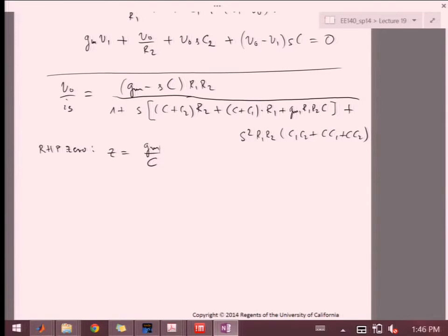And that will actually be very bad for us, as we'll see later in CMOS op-amp, because that's exactly the behavior you don't want to have. You want your gain to be lowered and your phase to be maintained, right? Because we want to decrease the gain below 1 over f in order to have gain margin. But what this does is keep your gain kind of flat instead of breaking it, while it drops your phase more quickly to pi, right? So then you quickly run out of phase margin, and you're left with pretty high gain for the loop gain, and then you're unstable. Okay, so those are kind of the things that we're going to look at in the next week or so when we look at CMOS.